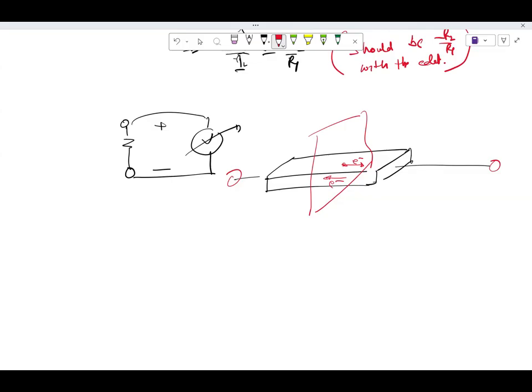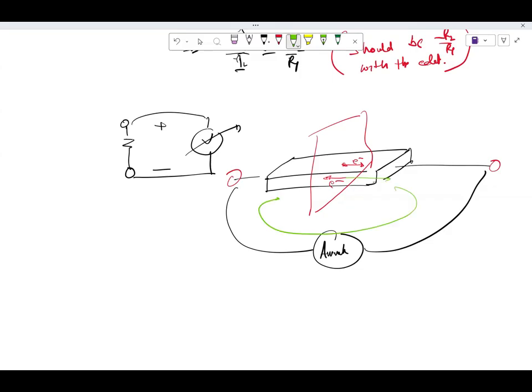So now what we are doing in this hypothetical experiment, we are saying that we are putting a voltmeter. Or even if you are not comfortable with a voltmeter in this analogy, let's say I put an ammeter, which is in principle a short circuit, right? So ideally it's a short circuit, which means the electrons that instantaneously were going in that direction have a path to go. And if it's an ammeter having infinite precision, I will see a motion of that arm, right? That is detecting current or electron flow through the galvanometer, even though I have nothing connected across it.